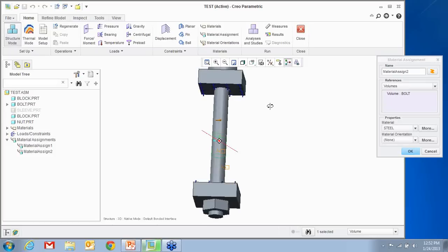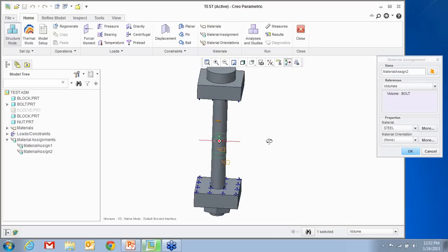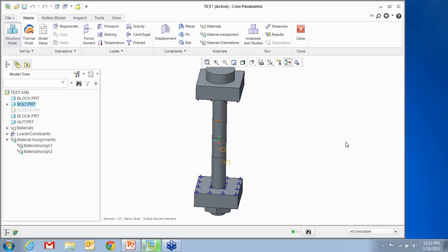And when the bolt is in tension, it is going to push down on this block and push down on this block, and you'll have the sleeve under compression. Now the theory is that you know how to solve the stress or a load in a bolt, a force by area. You can also use temperature and coefficient of thermal expansion to get the same kind of preload.